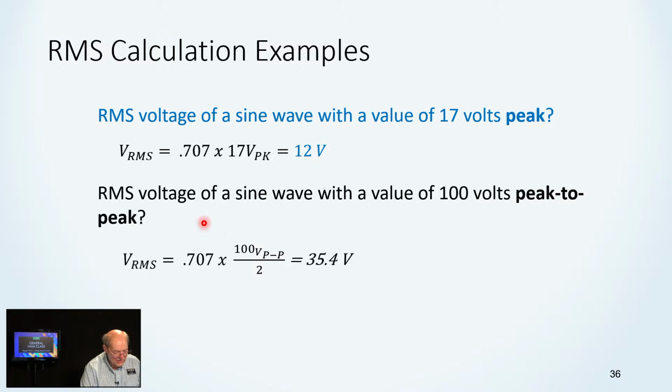And here's another one, RMS voltage of a sine wave. And this is a pool question. We'll see this again. Here's another one just for illustration purposes. RMS voltage of a sine wave with a value of 100 volts peak to peak. Okay, now none of our formulas are going to work on peak to peak unless we convert it to peak first. Well, in this case, we want to find the RMS voltage.